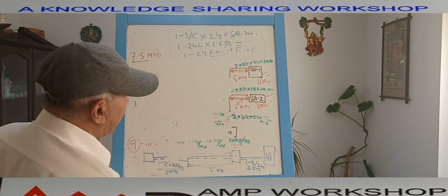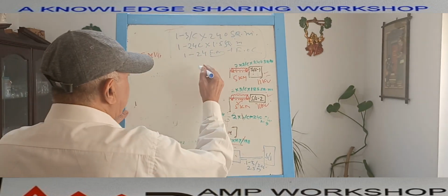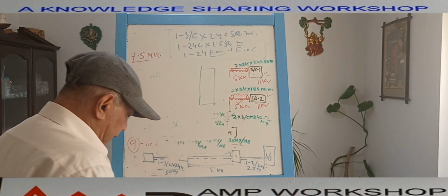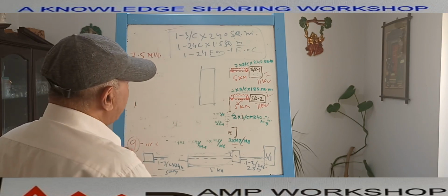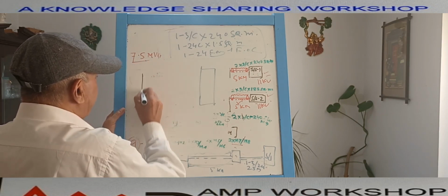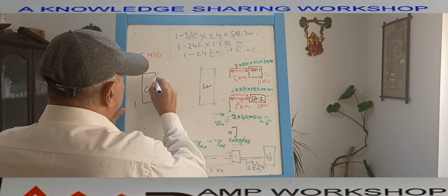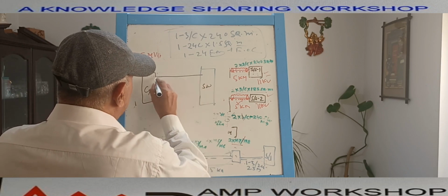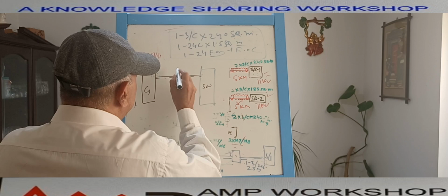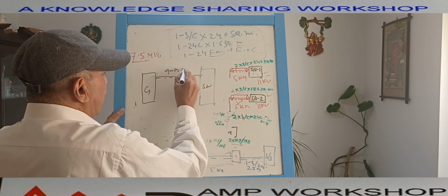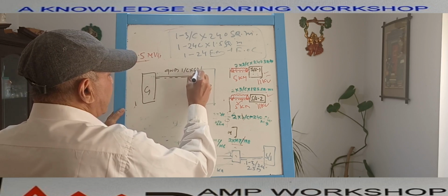In the same diagram, this is the switch gear we have shown, right? And this is our generator skid, right? These are the generators and this is a switch gear. We have shown that I have a power cable laid on the cable tray. This cable we have already shown; it is your 9 numbers 1 core into 630 square millimeter cable.